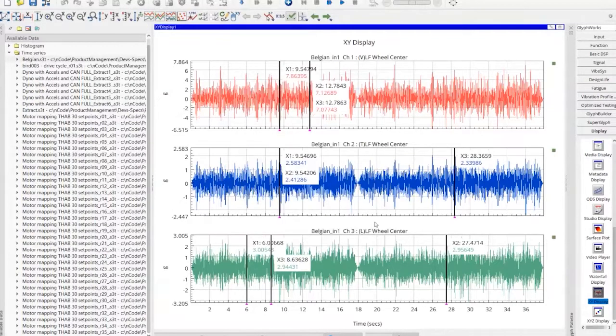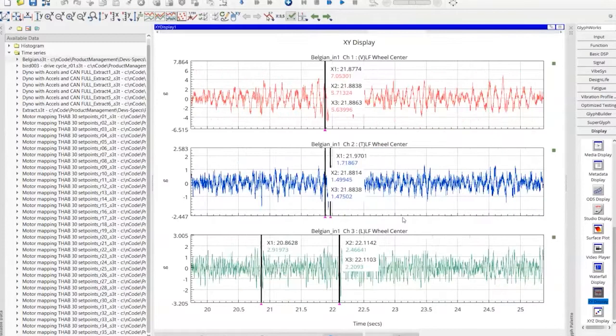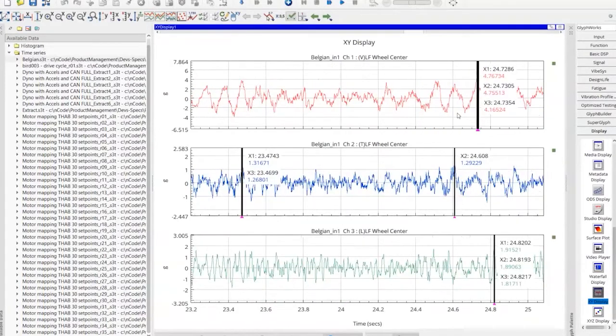If I go OK, let's take the green signal here. It's showing me the 3 cursors corresponding to the 3 peaks there. Now let's zoom in on the middle section here, and it's adapted, and now it's showing me the cursors corresponding to the max peaks in this zoomed area. Sometimes they're very, very similar, very close, if your signal is very peaky, very noisy.